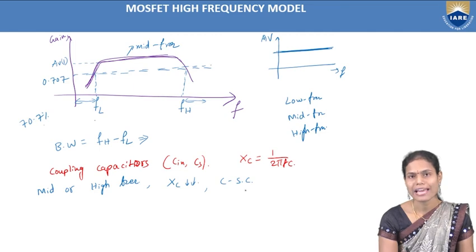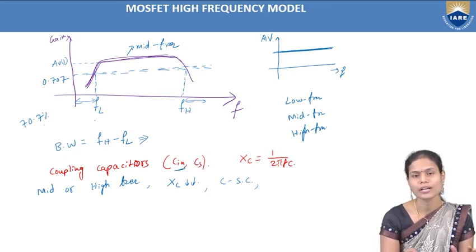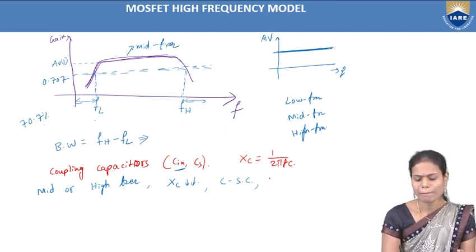Once the capacitor acts like a short circuit, it is able to allow the total applied signal to the circuit. The input coupling capacitor's function is to couple the input signal to your amplifier circuit. So the overall input voltage we are applying to the amplifier is coupled to the gate terminal of the Mosfet. If we are applying the maximum input voltage, ultimately at the output of the amplifier we will get the maximum output voltage.